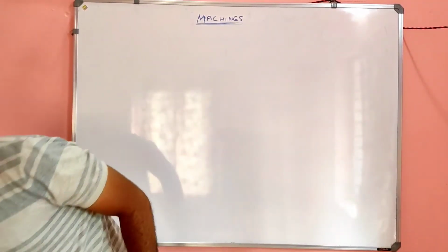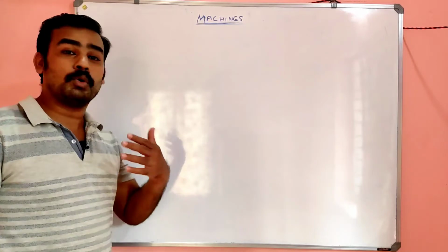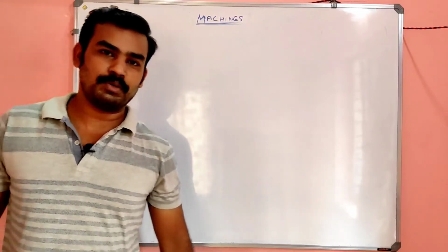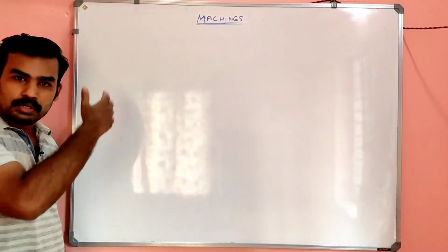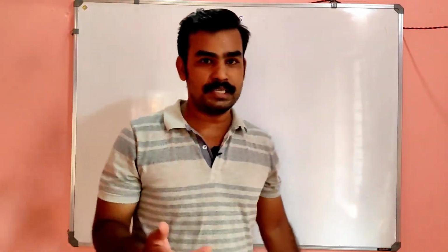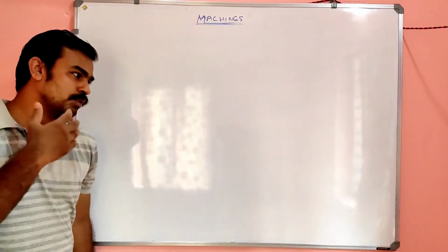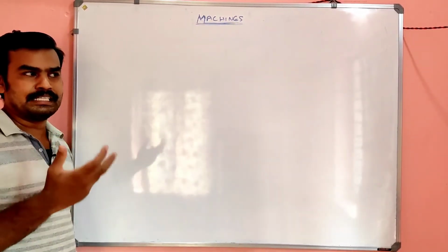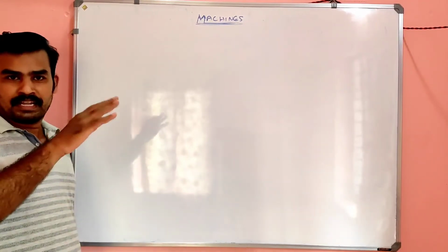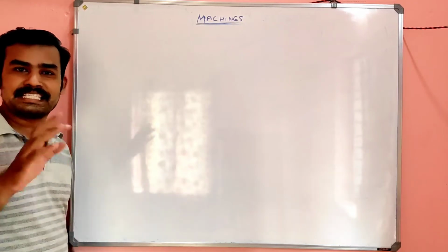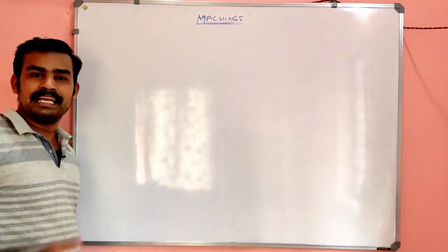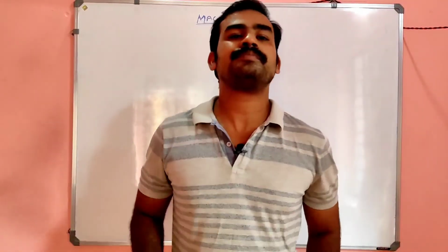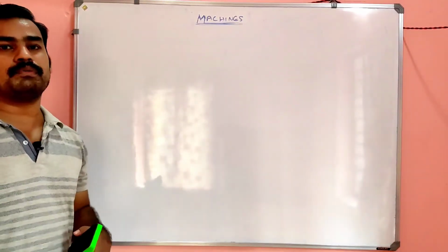So in the last class we did some torque slip characteristics and derived the expression for the conditions for maximum torque, full load torque, right? So torque slip characteristics and effect of the rotor resistance on the torque, for maximum torque, etc. And we derived the relation or the condition at which maximum torque occurs. Very important. That is rotor resistance R2 will be equal to slip times X2, R2 by S X2 is equal to S. That is the condition. So by doing some problems, it may be very helpful. These relations are very helpful while doing some problems.